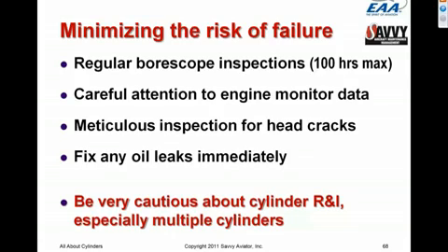But we want to be very, very cautious about who we allow to remove and install cylinders, particularly if we're changing multiple cylinders or doing something like a top overhaul. I've seen so many multiple cylinder removals result in catastrophic engine failures that on the aircraft that we manage, we try to avoid doing that. And if we absolutely positively have to remove multiple cylinders, we urge the owner to take the aircraft to an engine shop and have a real engine expert do it.